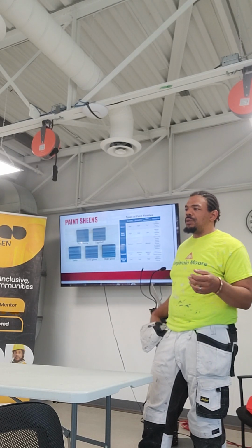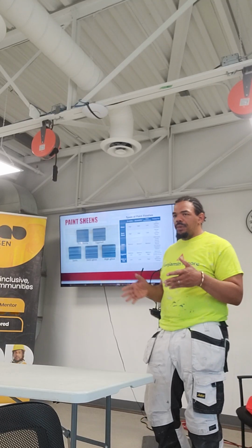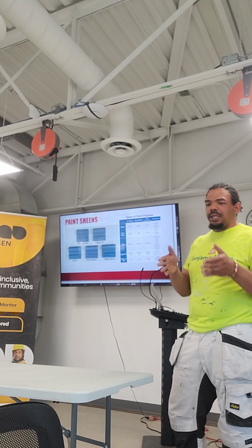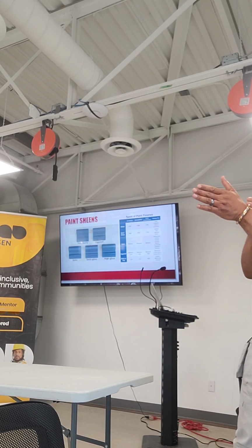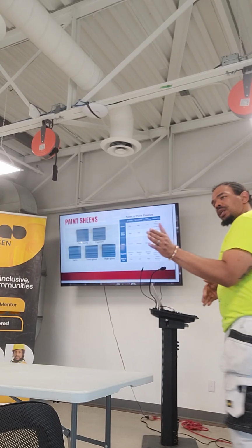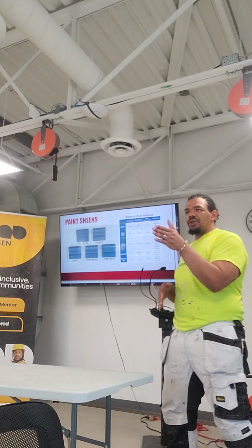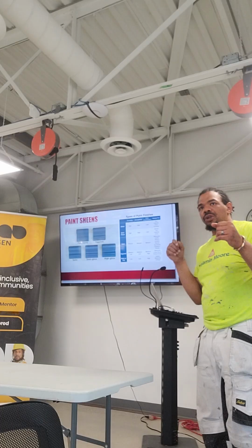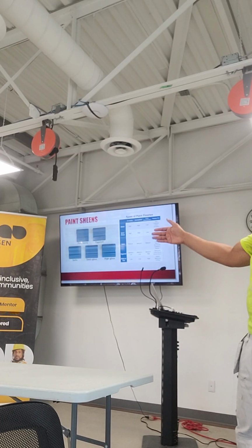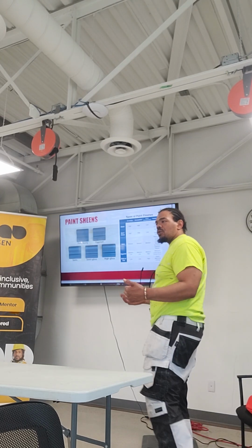And the imperfections show up because the gloss factor, again, the paint shines at such a high degree and from different angles from a higher degree. So what that means is, if this is 0, I can tell semi-gloss from 60 degrees all the way down to 0. So when we scale back and we come here and we're looking at a wall directly on, you can't really tell it's semi-gloss. But when you turn your head and you see the light bouncing off of it from this angle, that's how you know. When you turn your head one direction and it almost looks like a piece of glass, that's more confirmation that you're dealing with a semi-gloss finish. So understanding how the sheens work and how they work on angles is important.